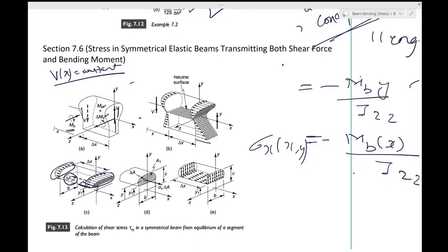Now you express the equilibrium requirement in quantitative form. There must be a force delta Fyx acting on the negative y face to obtain force balance. The top is the positive y face and the bottom is the negative y face. We show this positive shear force delta Fyx in the negative x direction, consistent with the fact that the face on which it acts is a negative y face.